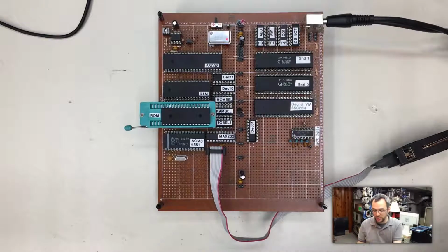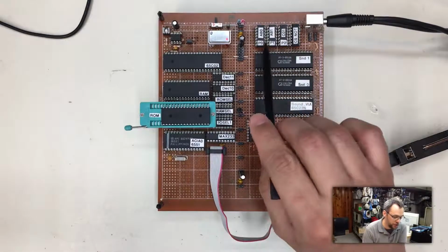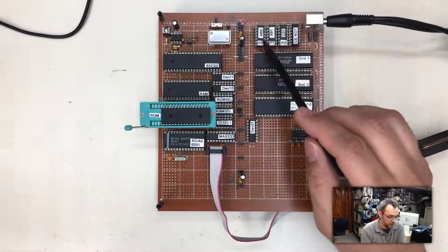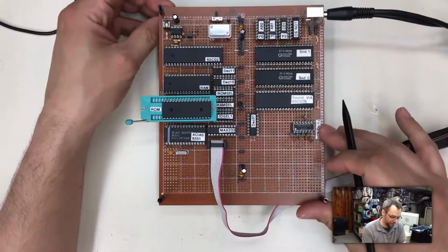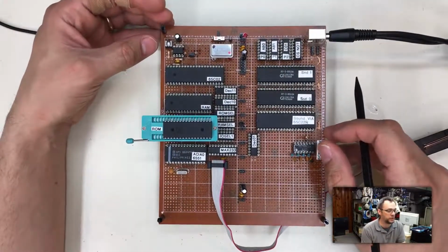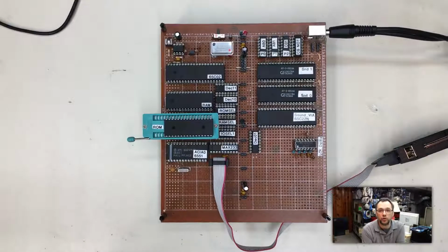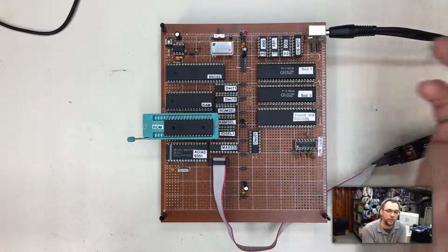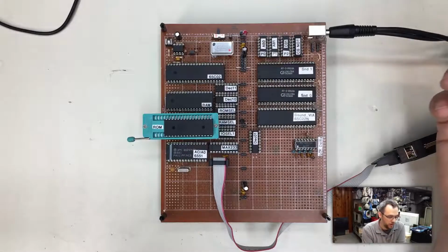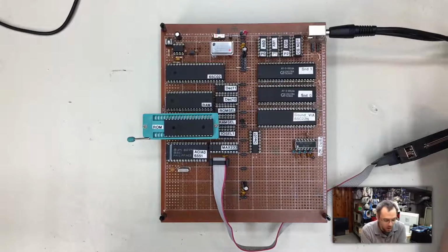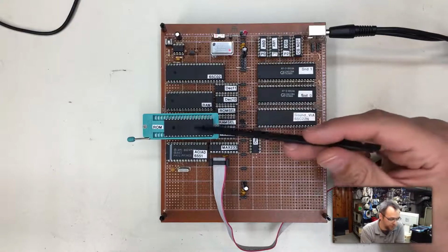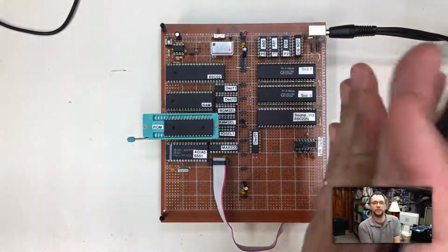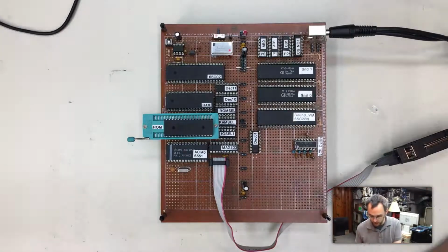Some of the downsides of these chips is that they do not have a reset pin. So that means if you hit the reset button on the computer because it froze up or whatever, the chips remember their last value, their last potentiometer position. So if things were slammed hard left and you have to reset the computer, it'll come back up and they'll still be hard left. That means I have to incorporate into the ROM code, which I haven't quite done yet, a little bit of code to forcefully reset the pots back to center on reset, but that's no big deal.